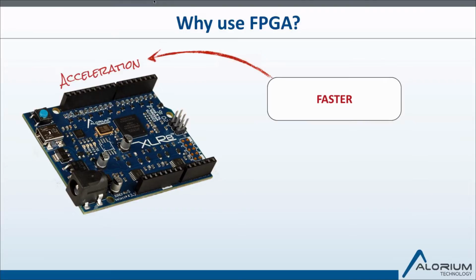If you take a function that's running in software, let's say on a microcontroller or some other type of small CPU, just about any time you can take that functionality and migrate it to some kind of custom hardware implementation, you are going to experience a tremendous amount of acceleration, and you're going to be able to run that way faster than you can running on an instruction-based processor. And sometimes we're even talking about orders of magnitude improvements for certain applications. So it's significant what you can experience in terms of improvement on hardware that's designed custom for running that function.